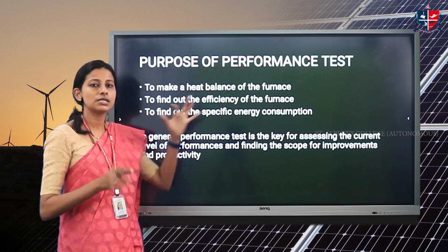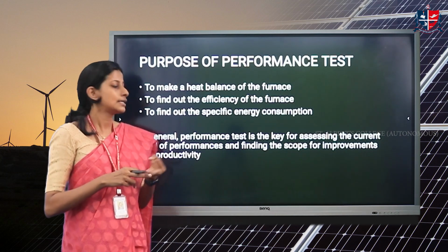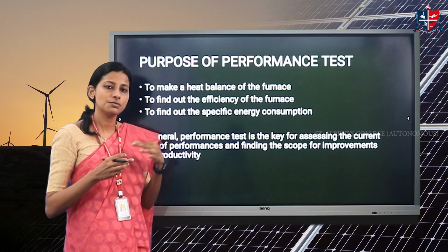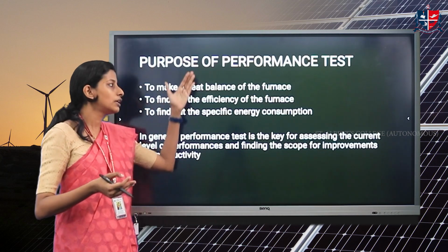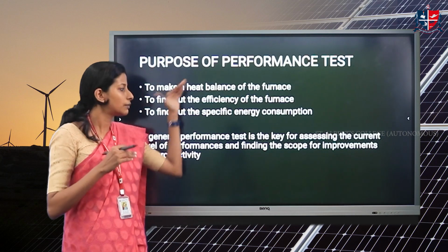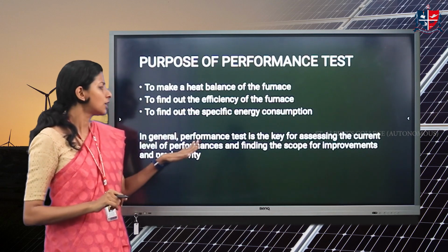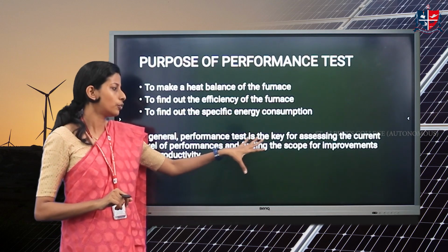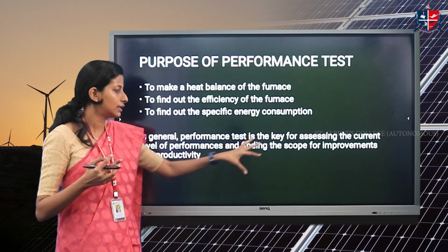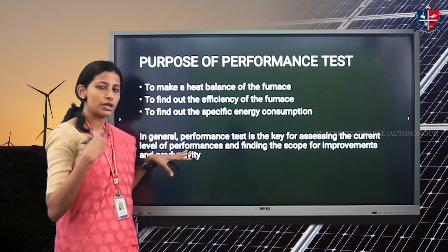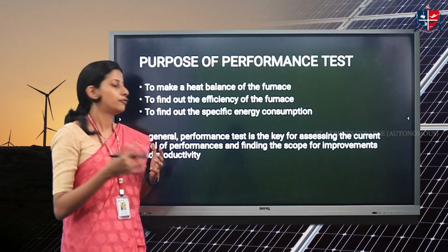So we perform the test to know the efficiency of the furnace, the energy consumption of the furnace, as well as the heat balance. Heat balance means whether the material is being heated up in proper proportion to the heat given. Only if we verify that it is working up to the standard can it be used in any industry or manufacturing plant. So in general, the performance test is key. It plays a very important role in assessing the current level of performance and finding the scope for improvements in productivity. You need to know whether any improvements are needed and whether the device is productive enough, and that is the basic purpose of performing a performance test.